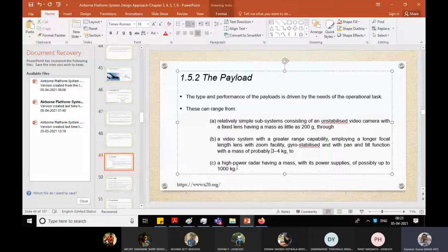This is not suddenly crossing 1000. Can you have 45 kg, 100 kg, 100 plus kg, till 1000 kg? Normally what you will see is payload capacity till 100 kg, especially synthetic aperture radar type of things on the UAV side. But if you go to very high altitude, if you're talking about a satellite-type airborne platform, and it has capacity till 1000 kg or more than that, then you can go with a very high capacity radar.